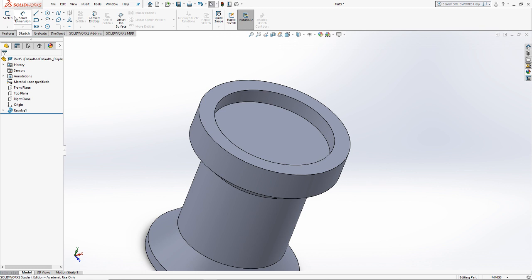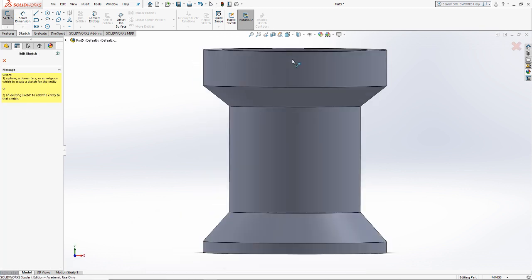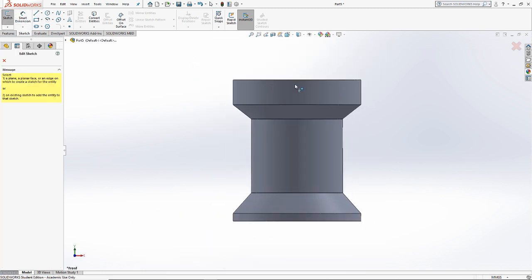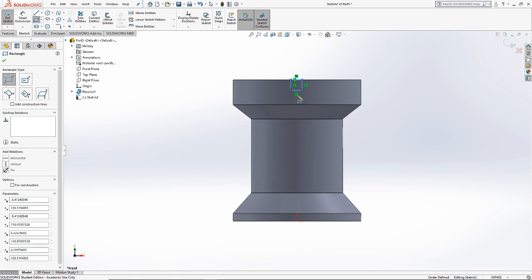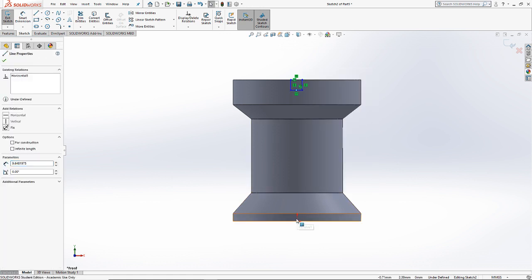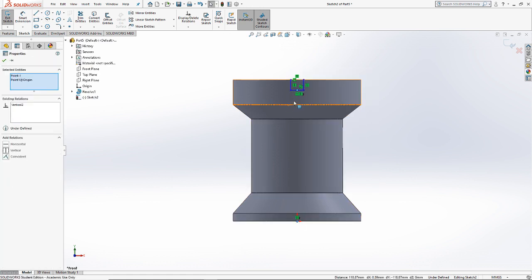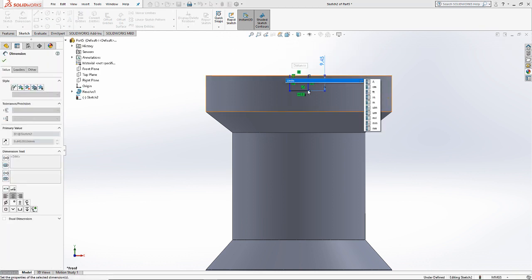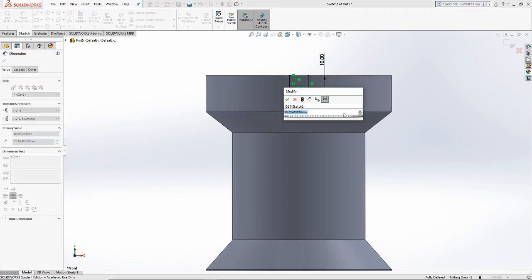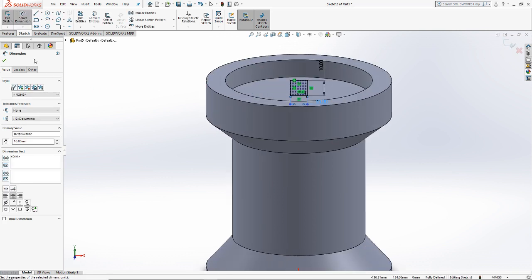So one option would be to draw on the front plane a notch, like, say, this. I can select the midpoint of my notch, tell it to be above the origin. I could apply a dimension that was just as arbitrary as everything else in this sketch that I'm creating.